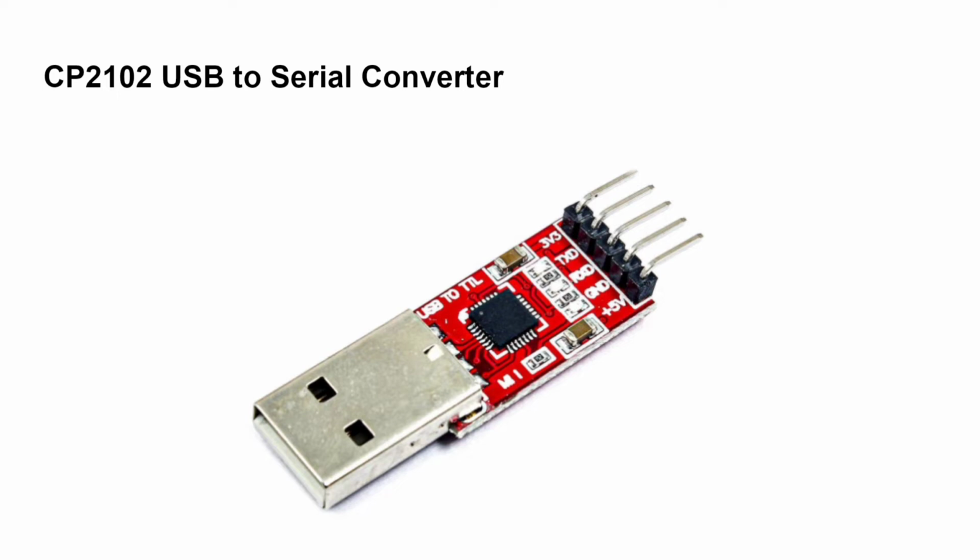Unlike the generic ESP32 modules, the ESP32-CAM doesn't support a USB connector. Therefore, in order to connect it with your computer, we need to use an FTDI USB to serial adapter. In our project, we use a CP2102 USB to serial converter.